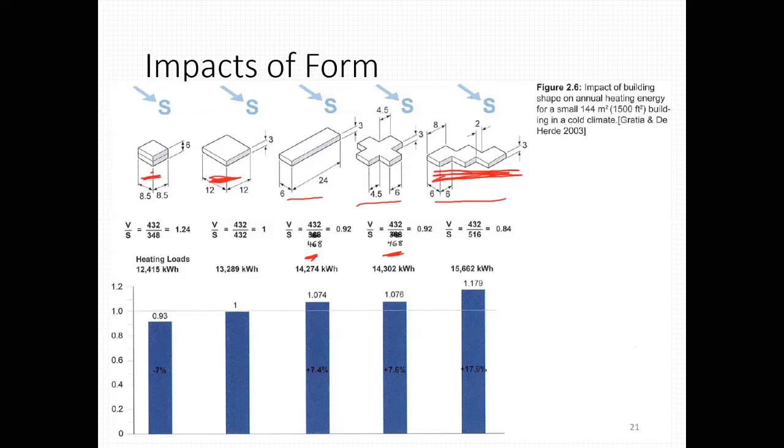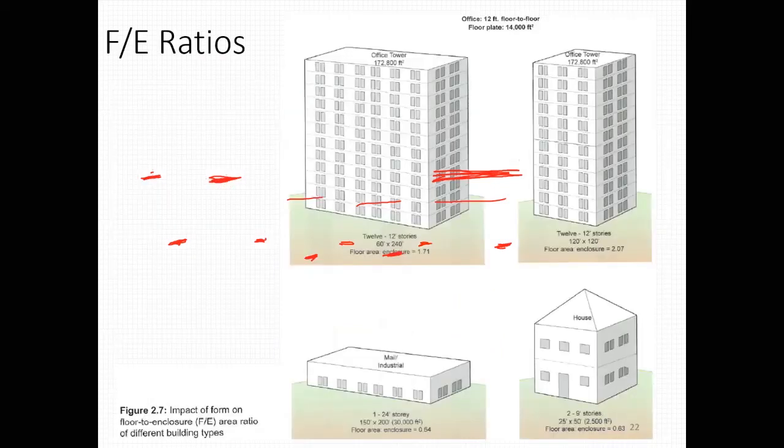So when we're looking at our compactness number, our two-story building has a pretty high compactness number. Even the one-story is still at 1. And then as you get into some of these longer or more complicated shapes, that number starts to go down. So this is the number that allows us to quantitatively assess our building form rather than saying it's a good shape, looks good, checks out, let's go with that design. We can slap a number on it and assess it quantitatively.